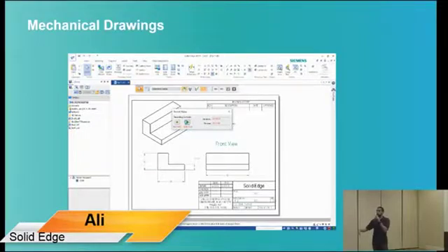So think about it. Dr. Marks, correct me if I'm wrong, but you have certain standards of what the drawing needs to look like, right? So you're probably familiar with drawing templates and stuff like this. This goes beyond a drawing template, because with the Quick Sheet you're defining what those views are, and you simply drag and drop that part in there. All the dimensions, all the section views, everything comes up and it's already done, right? So you can build a Quick Sheet based off of the template or what the standard is for the solar car, and have that already at the ready and create your drawings very, very quickly.